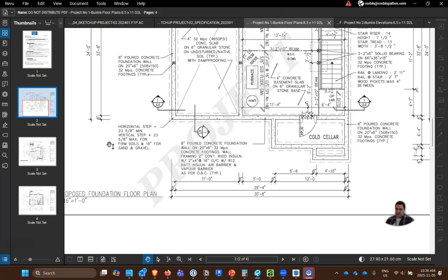In here we see our 2x10s at 6 inches on center. That's our floor type for the floor above, because we're seeing what we're framing above there. The second number we have is our 5/8 subfloor. So let's bring those in. We have our 2x10s and our 5/8.